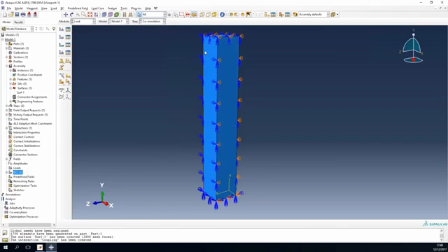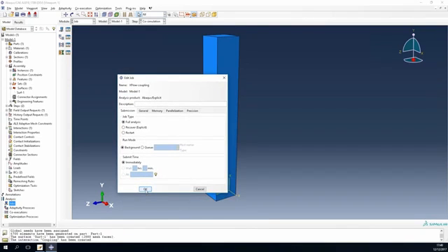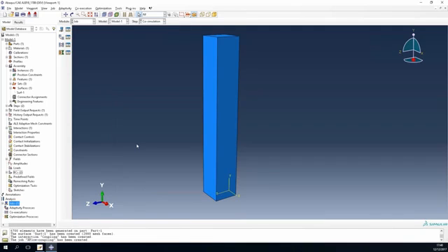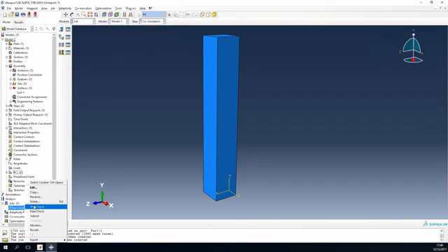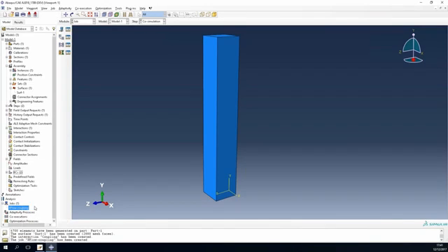So we have our setup in Abaqus. Let's create a job, and let's call that XFlow coupling. Okay, and let's keep the standard settings. I'm not going to do anything fancy. And once we are here, we are ready to run the co-simulation. So we're going to write our input file for this Abaqus simulation. So if you right click on the job and write input, now we have our input file, and then we're going to use that to run our co-simulation.